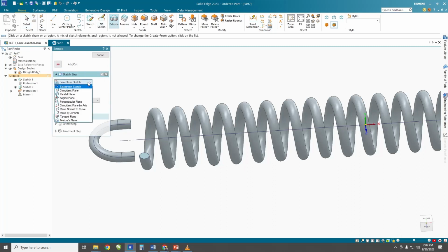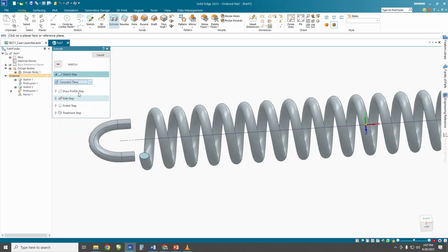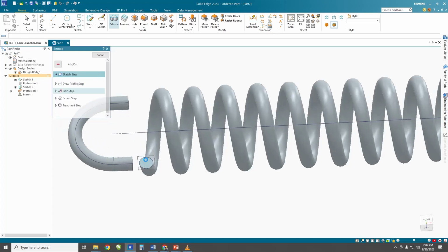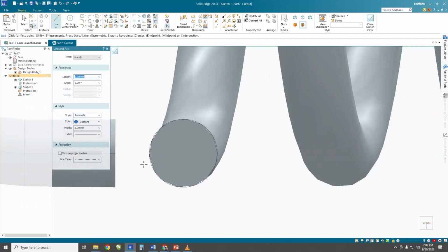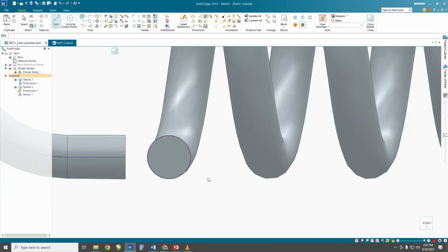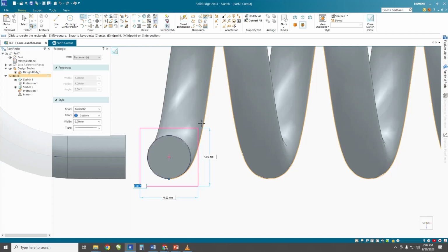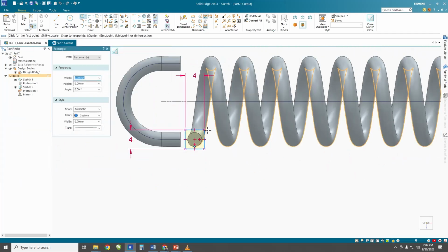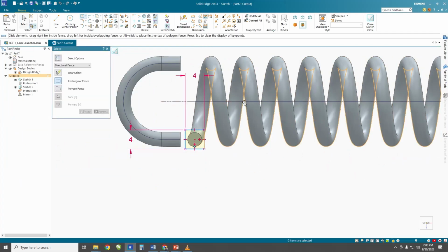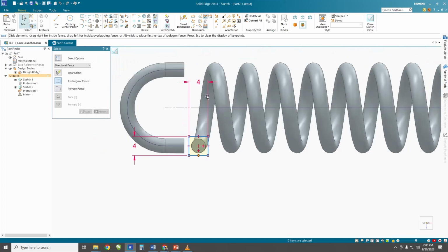But rather than select from sketch, we're going to draw our own on this surface. I'm just going to make a box, and we're going to give it dimensions. Whatever you make this so that it cuts it out, we want to make sure to give it dimensions so that when we do our stretching, this doesn't get changed around and messed up.